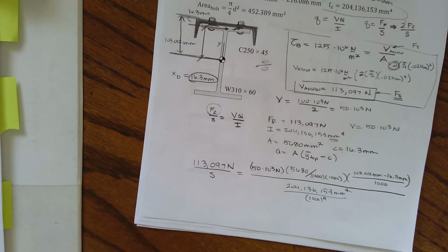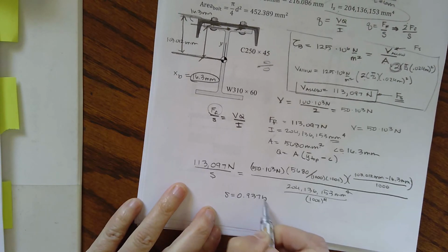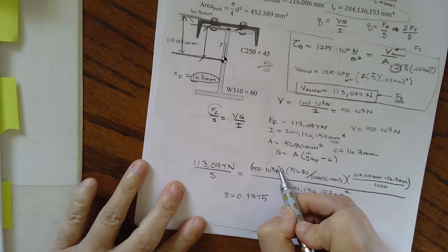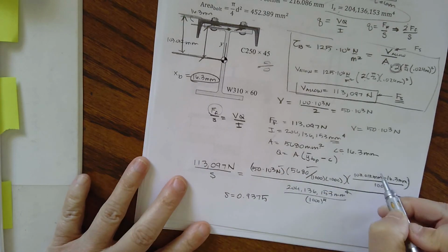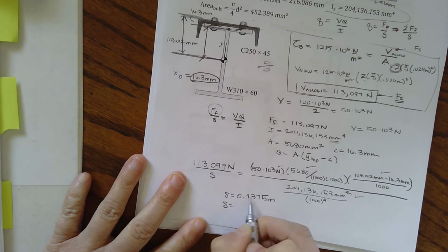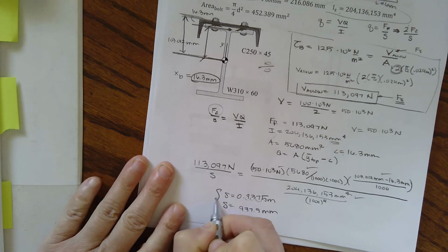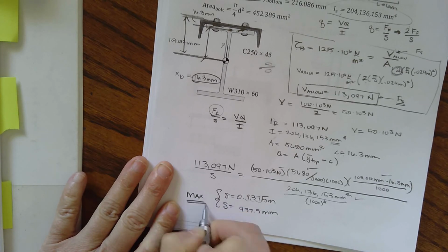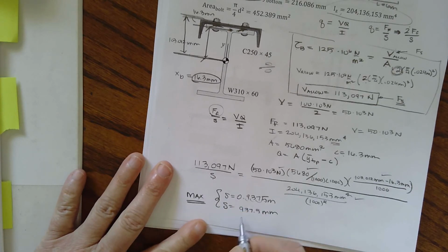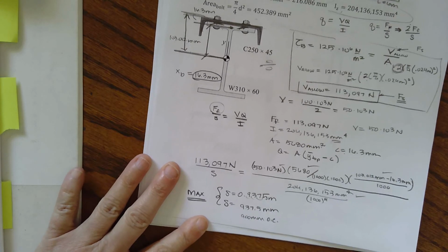And then we can go back and calculate this spacing. And so when I do that, I get a spacing of 0.9375. And let's think about our units. We are in newtons. We have converted millimeters to meters, millimeters to meters, millimeters to meters. So if we wanted to look at millimeters, 937.5 millimeters. And again, this is the max that it can be, maximum. So we might round down to 900 millimeters on center, because we want to round down.